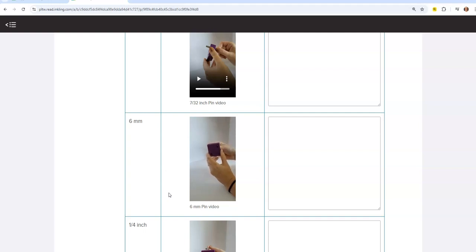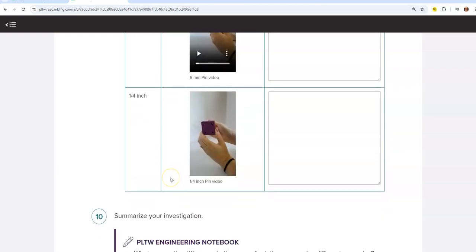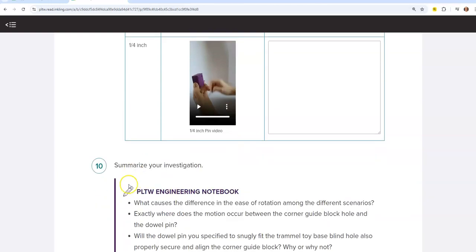As we take a look at these now, we want to see, is there any friction on that? You can turn that, but that one turns, but not quite as much. That's a little bit more of, let's say, a transition fit between the two. Now, if you have to really struggle to get any of them inside the part, now this one right here will not fit. It's a total interference fit. Cannot even fit that one through.